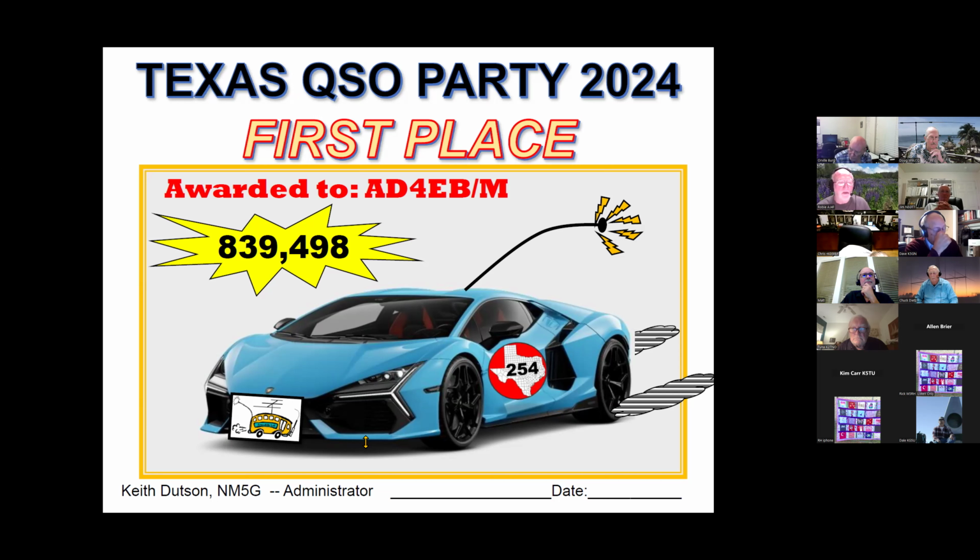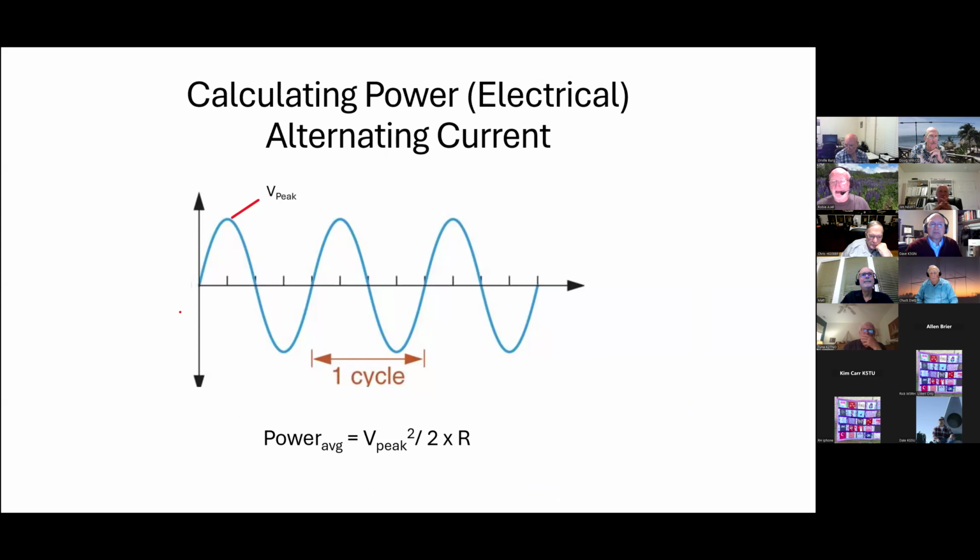Now, if you go back and look at my waveform here, there's a rule about digital sampling to get good data. Nyquist, yeah, the sampling frequency. So here I am designing my watt meter, and I'm going to sample here and here and here and here and here. No power, right? Widely varying results. But the Nyquist criteria says if you sample it frequently enough, you can get a good representation of what this wave looks like. I forget the number, I used to know that kind of stuff, but say 10 or 20 times the frequency of this wave. If you sample it that often, you can get a very good representation of the wave.